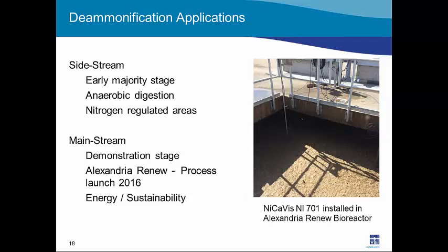There are a couple deammonification applications out there today. One of them is side stream treatment. This technology is in what is considered the early majority stage, in that it's been implemented in full scale at many, many facilities. So it's reached a status of maturity. Typically, the facilities that use this would have anaerobic digestion.